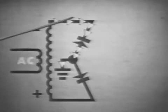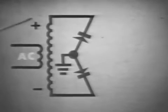Another diode connected to the top of the secondary will accomplish the same thing. It'll connect the top of the secondary to ground when it's negative, and open this path to ground when the top of the secondary is positive. Now watch as these two diodes work together to always connect the negative end of the secondary to ground.